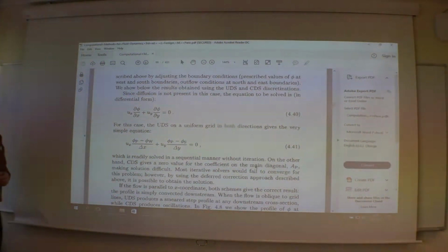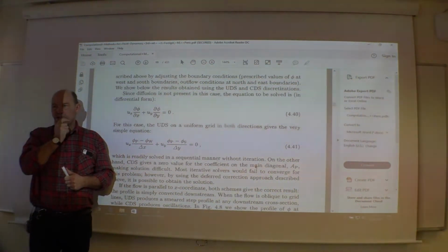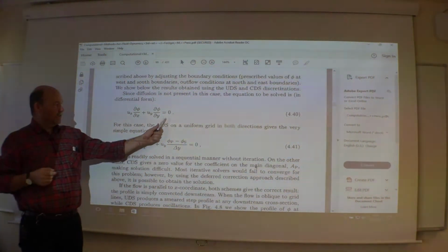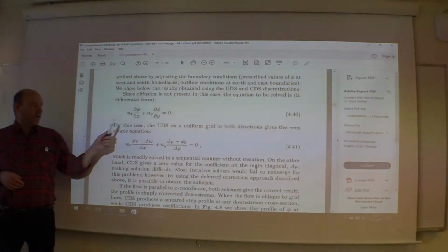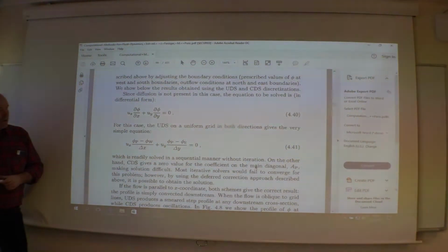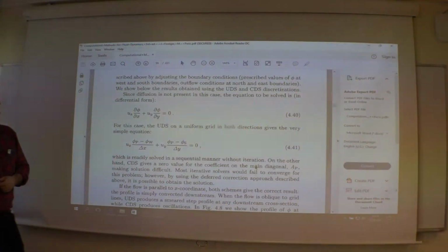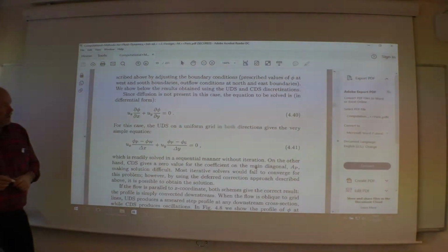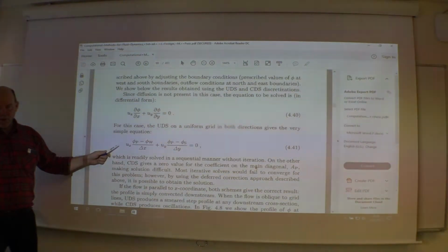Change the equation. Put gamma equal to 0. Then we don't have any diffusion at all. So we are left only with the convective equation, the convective terms. And here we are in trouble, dead trouble. So we can have a look at it afterwards with the central scheme. Here we have jumped directly to the first order upwind scheme.